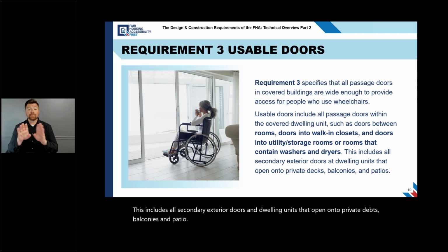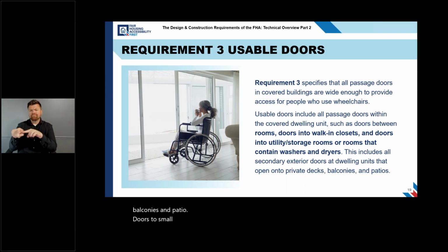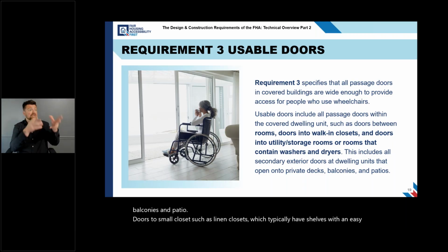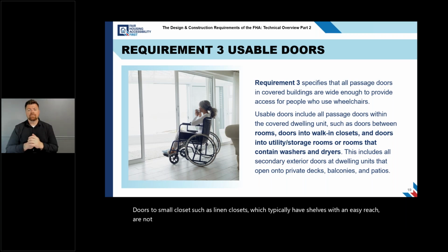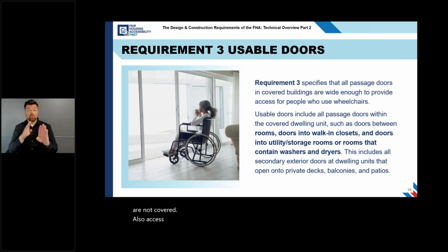Doors to small closets, such as linen closets, which typically have shelves within easy reach, are not covered. Also, access doors to small mechanical closets dedicated specifically to furnaces or water heaters are not covered.